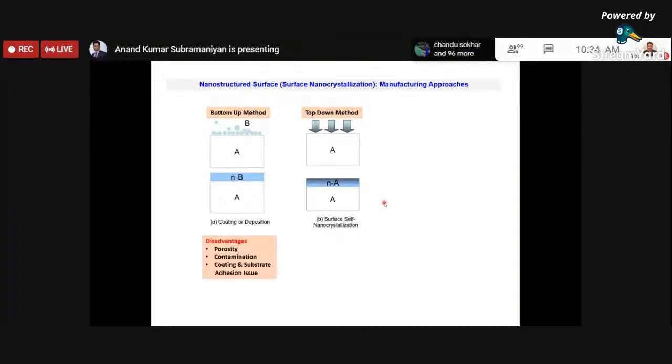So now, if you look at the bottom-up method, there are certain disadvantages this method has, right? For example, you can encounter porosity: when you start depositing, if there are certain gaps, that is what we want to avoid, and we call it porosity. So you can expect porosity with this technique the moment we employ it. And we can also expect there could be contamination: basically we are trying to deposit material B on a material A, and at the interface there could be a mixture of A and B, which is undesirable. That's what we call contamination.